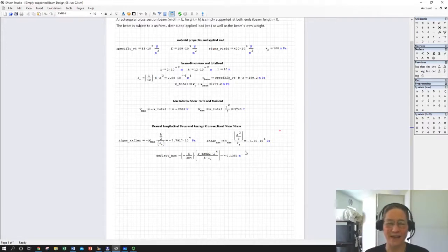If it was a bridge deck, that would be a place water could accumulate, not good for traffic or for pedestrian safety, and not good for corrosion if we want to keep things dry most of the time. Not underwater. If it sagged a lot, we could start accumulating a snow load, which would mean that this might be higher than it was intended to be. Roofs can fail because of that.